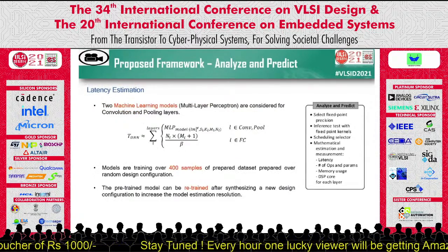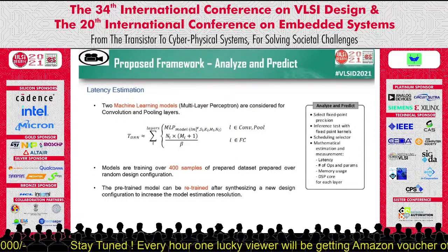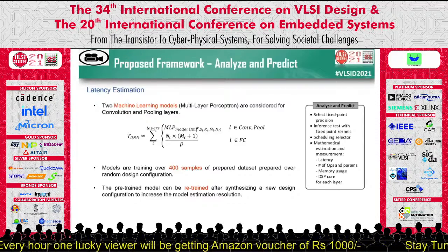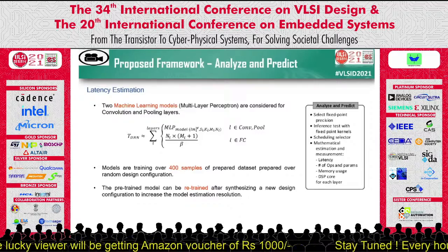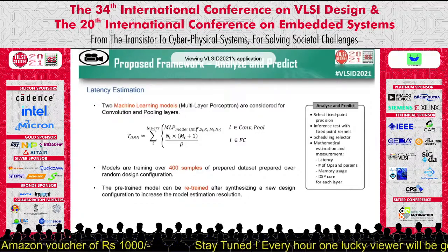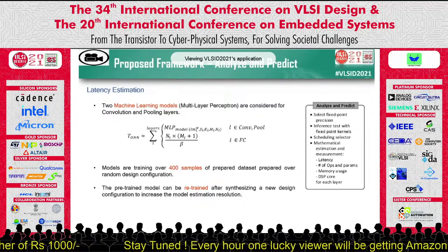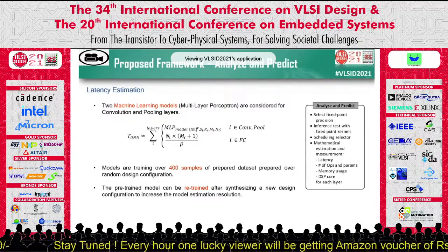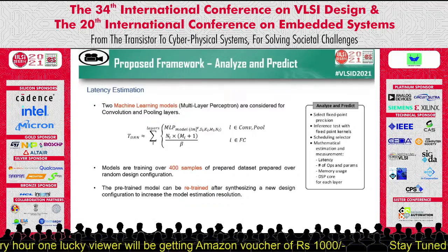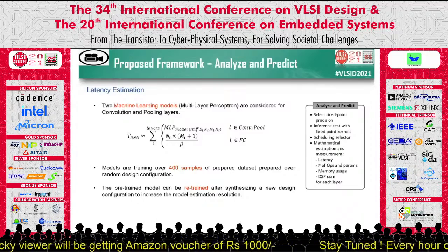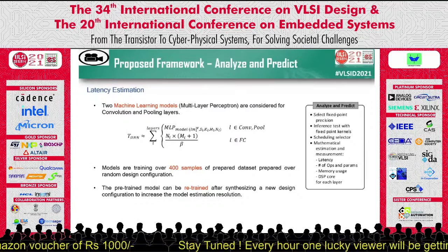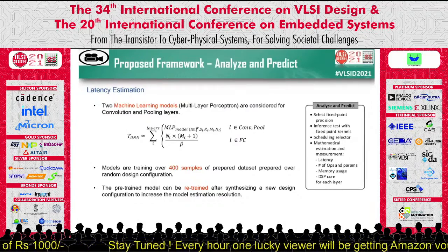In this work, only the convolution and pooling layers are modeled for the estimation using a multi-layer perceptron, because of three reasons. First, the accelerator for the fully connected layer has a linear relation with the input-output size. Second, the fully connected layer computations can be transferred to the soft or hardcore processor; its computation depends on the software code. Third, the fully connected layers are memory intensive, and their performance depends on the memory bandwidth and latency.